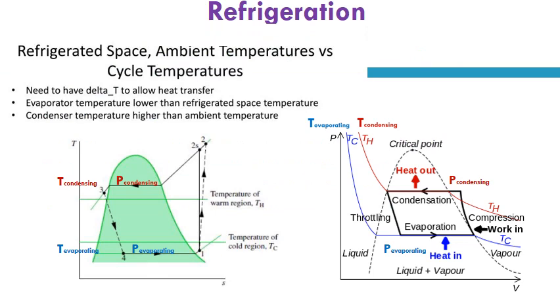This slide shows a presentation of the vapor compression cycle on both TS diagrams and PV diagrams. It should be clear that the cycle is working between two main pressures: low pressure in the evaporation, which may be named evaporation pressure or evaporator pressure, and high pressure side, which is named condensation pressure or pressure of the condenser, as can be shown on both TS diagram and PV diagram presented here in this slide.